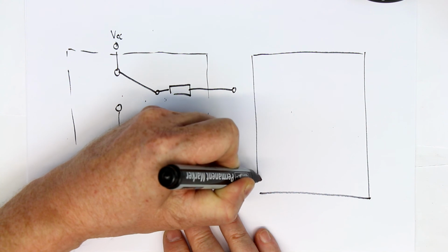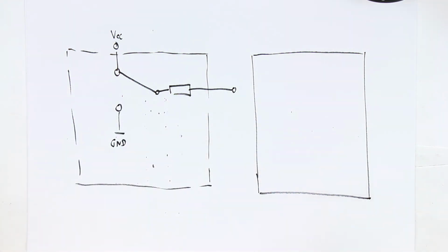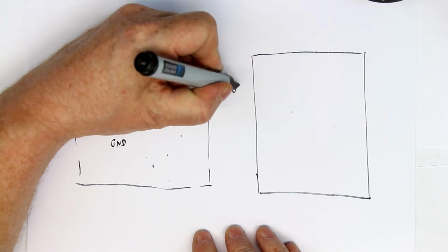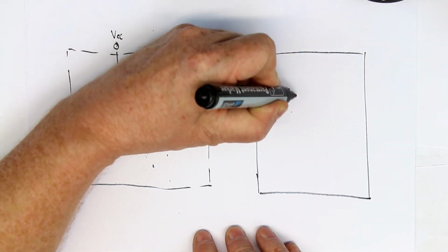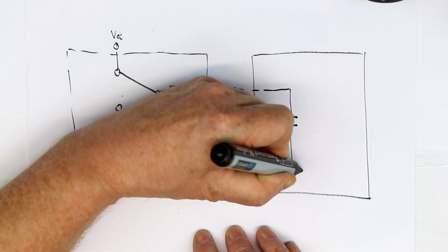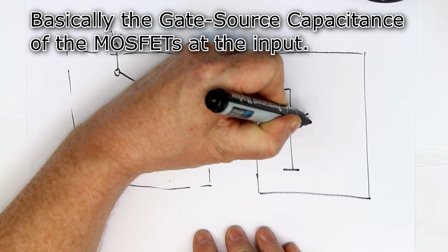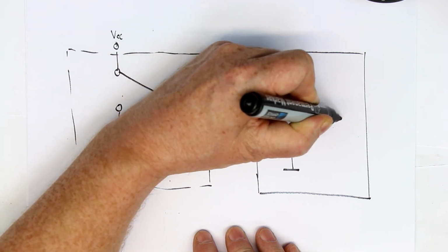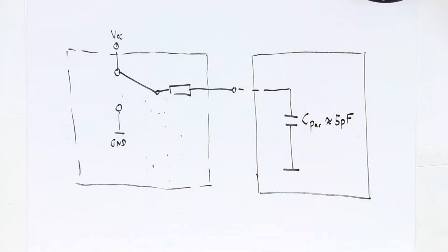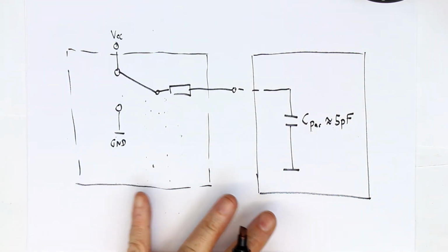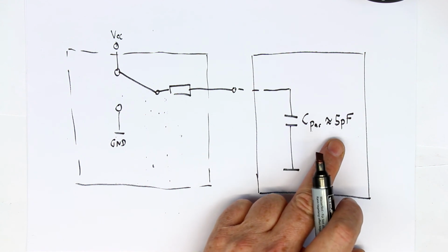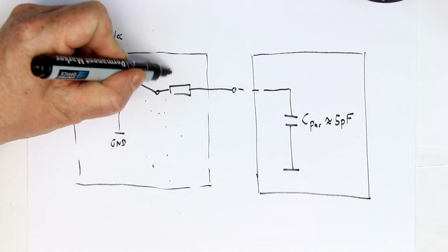And what does that consist of? We leave out the ESD protection diodes, etc. But every input has a parasitic capacitance, and that is always in the range of around 5 picofarads. If you compare the different logic series available in CMOS, you will always find this is very near to 5 picofarad, might be 3 sometimes, or in standard CMOS logic a little bit higher, but we take as an average 5 picofarad.